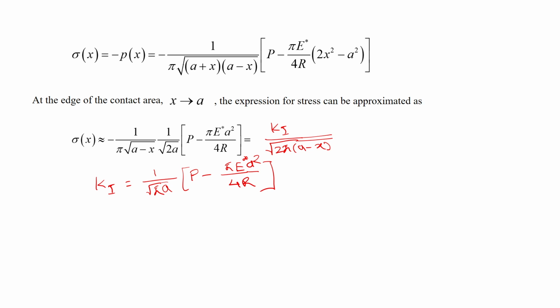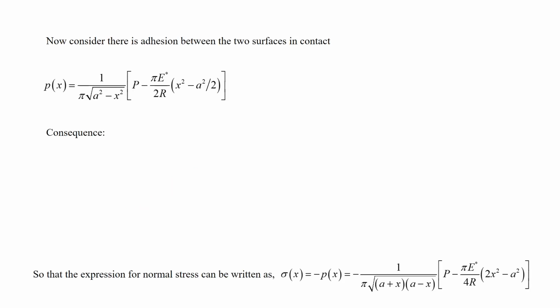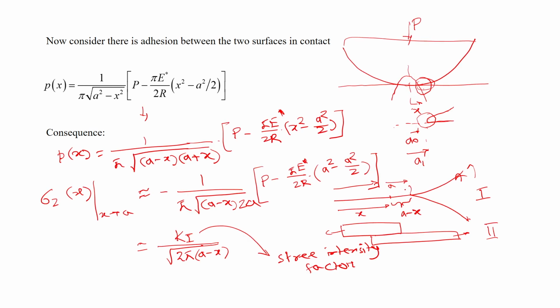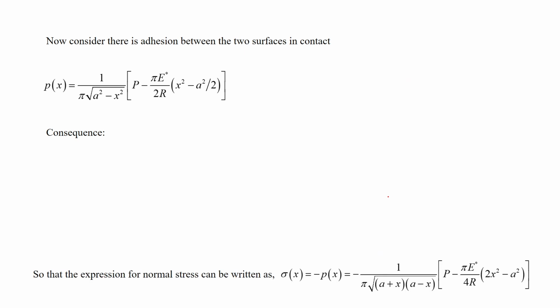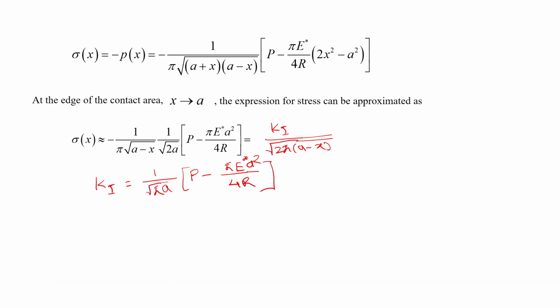So, this is one idea that we have borrowed from fracture mechanics. Now, why did we do this? Because in fracture mechanics there is a way to calculate the strain energy release rate. What happens when this crack propagates, the energy that is stored because of the tensile load gets released. And fracture mechanicians have developed a way to calculate that energy that gets released. They call it G, and that is called the strain energy release rate.